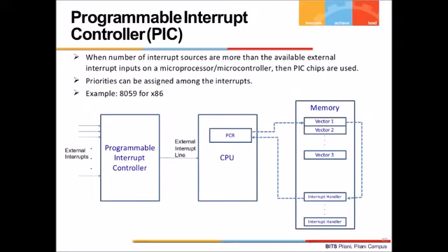So we can look at this from a block diagram perspective. You can see that we talked about one interrupt, right? The CPU will have a few interrupt lines, but we may have multiple peripheral devices which we would like to interrupt the CPU. Generally, these peripheral devices operate in interrupt-driven mode. Whenever they have something, they'll interrupt the CPU. Then the CPU will execute the requested action by them, and then they'll go back.